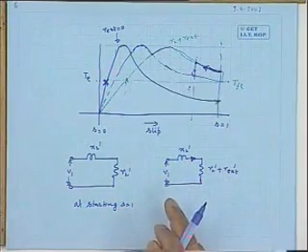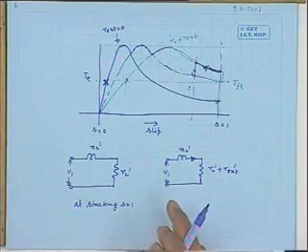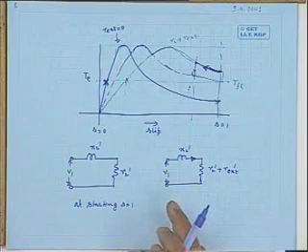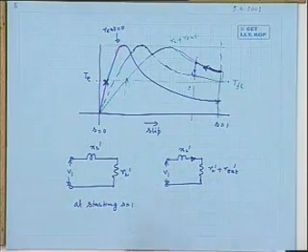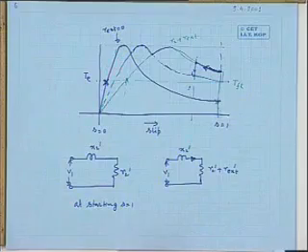It will be less, because impedance in the circuit has been increased. Is it not? So the starting current is reduced, no doubt, but the starting torque is increased. Is it not a contradiction? Because torque is BIL. Suppose current is decreased, how can torque increase?